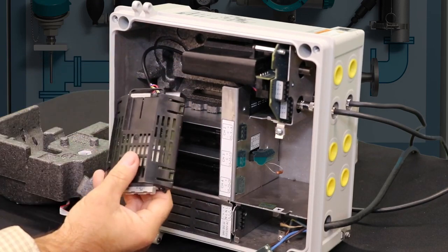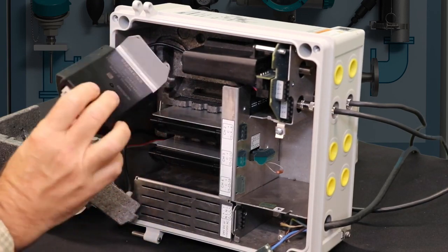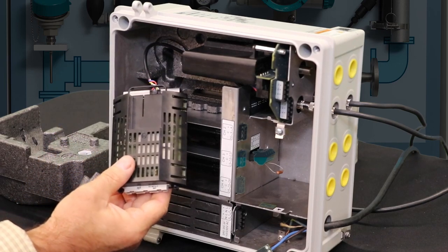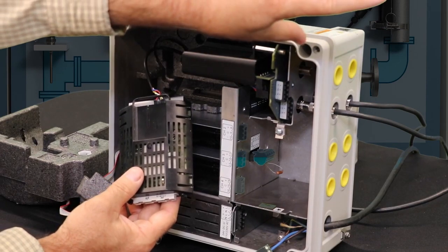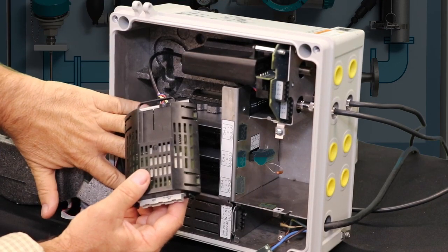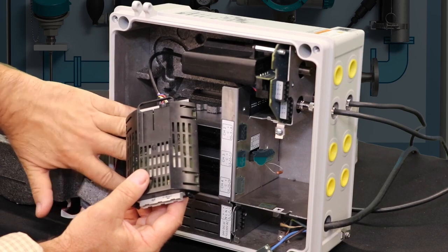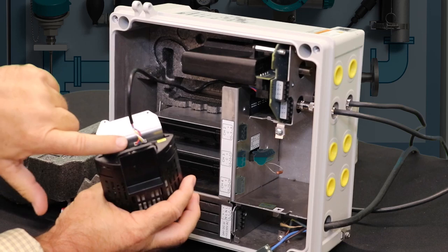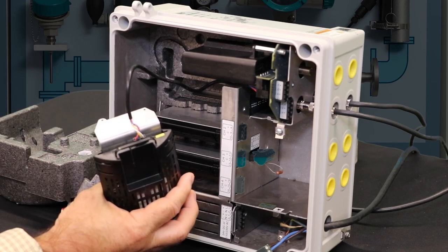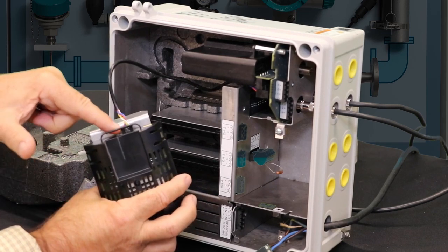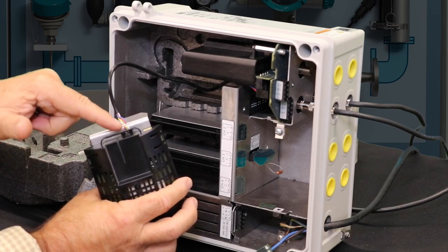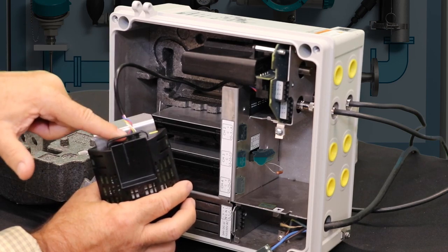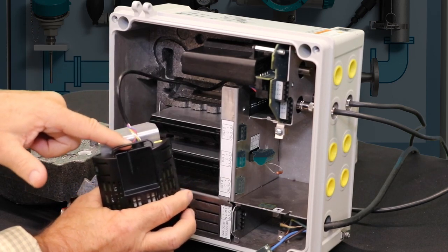And the last one is the barrier cassette. And this is what acts as isolation and protection between the outside world and the transmitter, and the rest of the transmitter internally. And if you notice, the other end of this cable gets plugged in here at the top of the cassette. And you'll also want to check and make sure that this is not loose if you have that DSL error code that we saw.